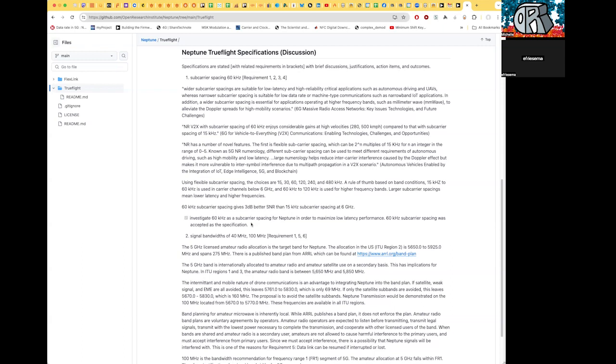The reason that I asked about that is because your choice of subcarrier spacing is somewhat frequency dependent, and it also directly affects the latency. A 60 kilohertz subcarrier spacing is the one that people use for 5 gigahertz and above, and 15 is a divisor of 60, and that's why the numerology works out. When you design a system for 15, it's a compromise, but 15 and multiples of 15 are what people look at. We really do want to use 60 kilohertz.